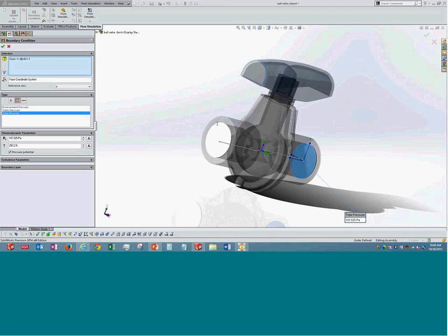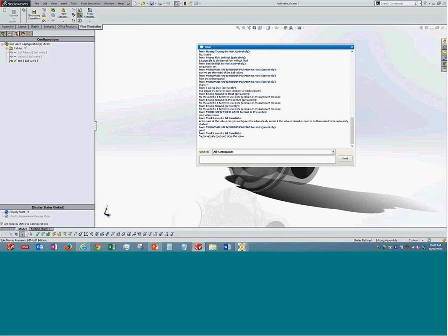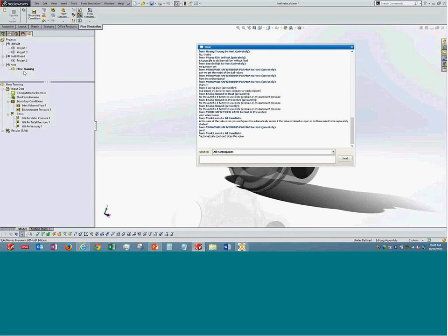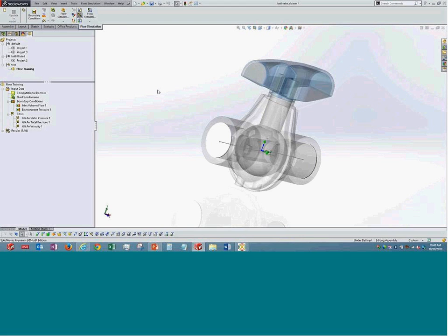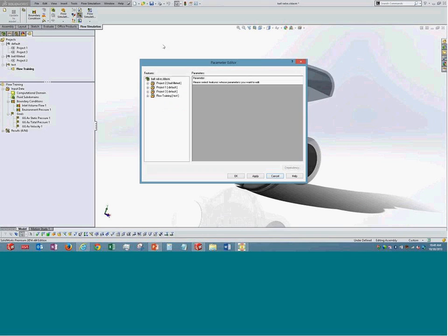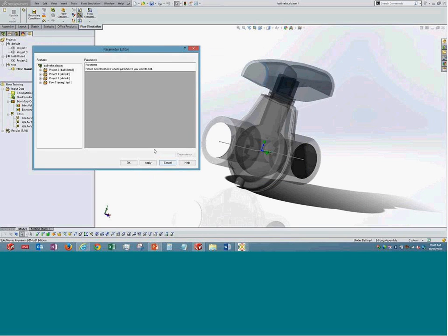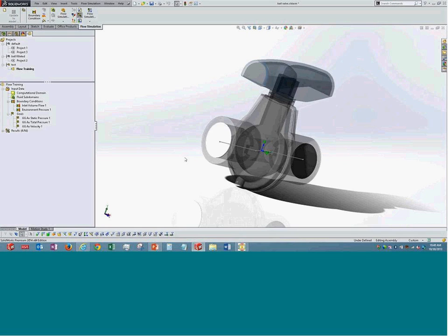We specify different angles for the wall, and we can solve multiple iterations using that. Finally, I think it is called automatic over here. How that works is we specify the details of the actual location of the wall, and the software can do the calculation for us. From the parametric option or parameter editor, we can use some parameters on which it can iterate and solve it for us. There are no further questions.